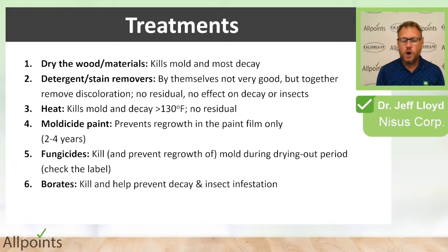It's really not a good thing to do to be painting wood in a crawl space or inside walls. What that typically does is, first of all, it won't stop any fungi growing in the wood. It only stops fungi growing in the paint film, number one. And number two, if the wood is still wet, or if it gets wet again, it reduces its drying rate and typically makes it rot faster. So not a good thing to do.